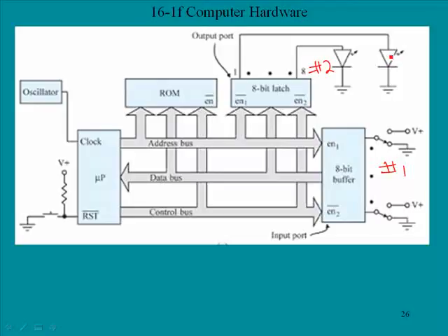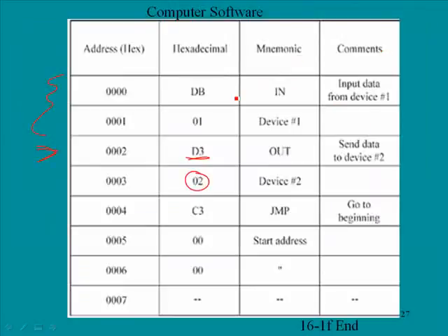Notice the process so far has resulted in the states of the switches being displayed on the LEDs. There were, of course, a few nanoseconds or microseconds of delay in the accumulator. The microprocessor now outputs the program counter to the address bus and memory read to the control bus. This is the same thing we've done before as we read the contents of ROM. Down the data bus from ROM comes C3, which is our next instruction.